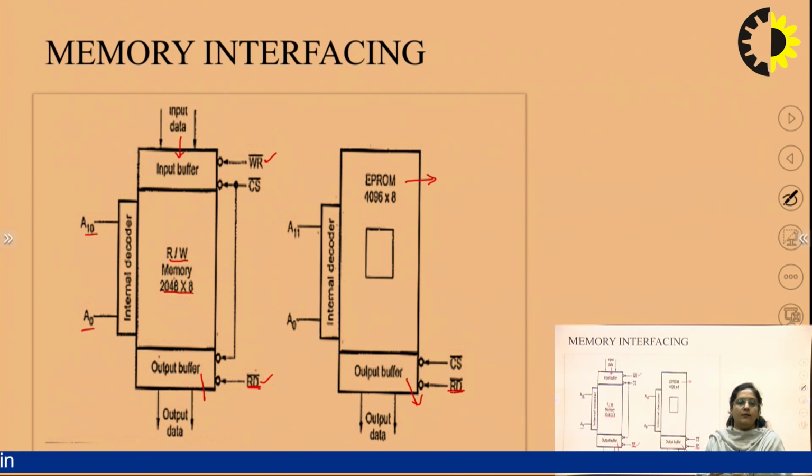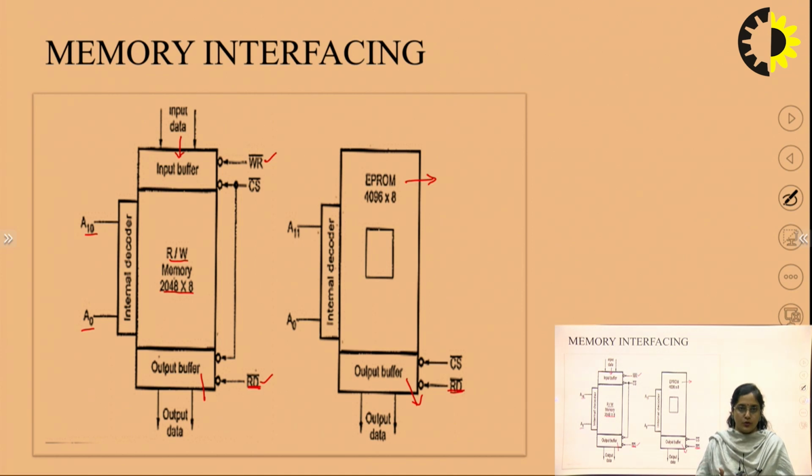If we are using more than one type of memory in our microprocessor system, we have RAM also, we have EEPROM also, we have different types of memories on our kit system. Then in that case, whichever memory microprocessor is dealing with, whether EEPROM or whether it is reading or writing something from read write memory, it has to select this memory.